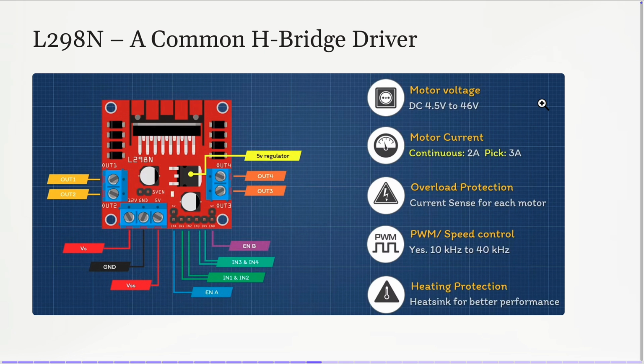Okay, and this is what we implement here in the controller of the Arduino on how to control the speed, whether we want to move straight forward or we want to rotate. And also what is the speed that I want the robot to move with, which is based on this particular pin, which is called the enable pin. Look now, everything is duplicated because we will control two motors.